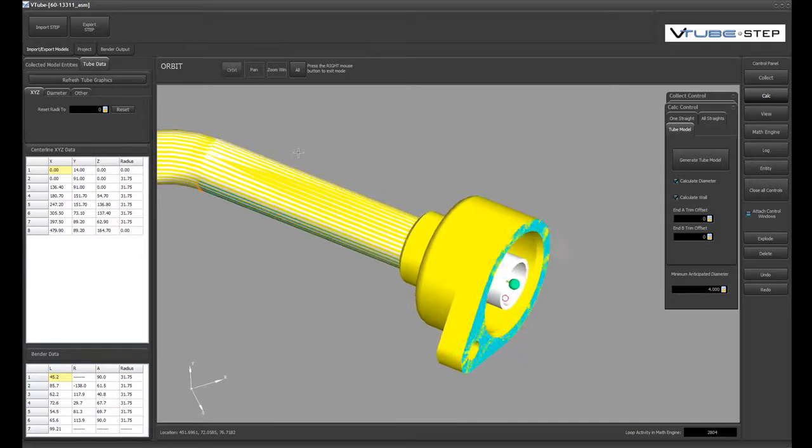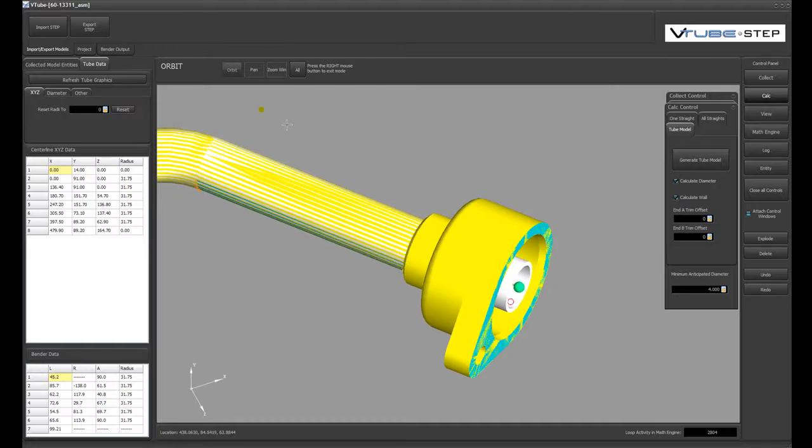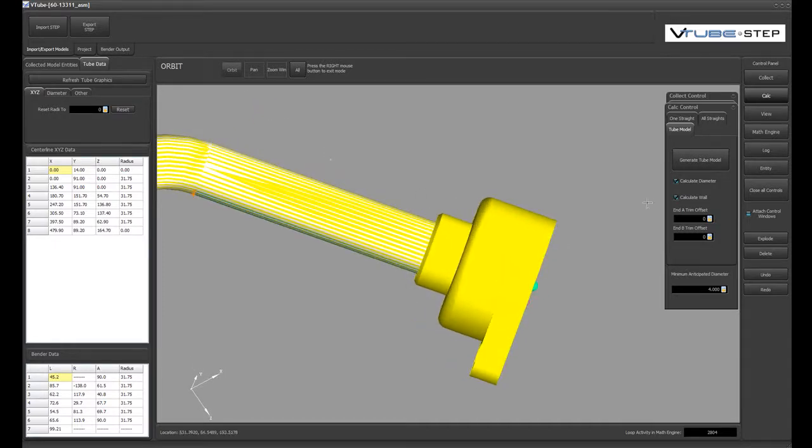Any surface geometry can be selected. It doesn't have to be just a surface like this. It can be any shape, and the centroid will then be used to perform the trim. Now let's say that this is not precisely the endpoint of the tube, but it's somewhere else relative to the surface of the end of this geometry. We allow for offsetting the endpoint.